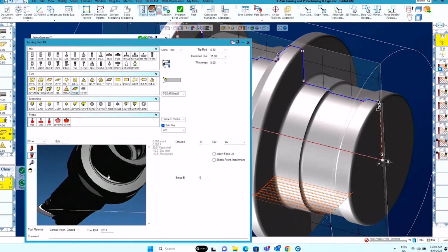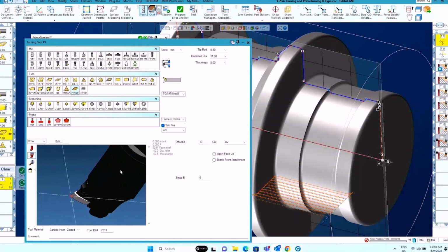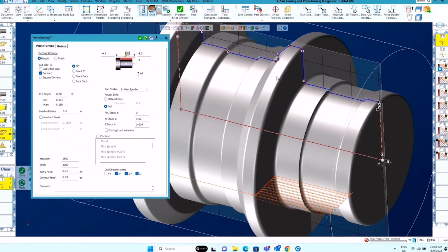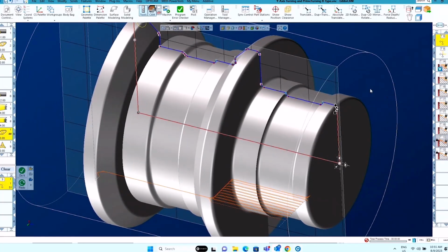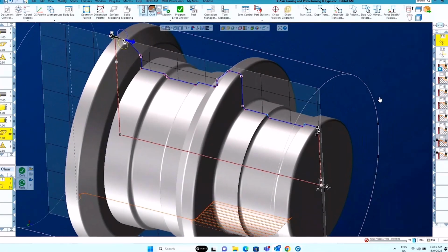It's designed like this, so the system knows automatically that my toolpath has to be created in the y-axis plane and not in the conventional x-axis plane. And this is actually how easy it really is to go from conventional machining within GibbsCAM to y-axis machining in GibbsCAM. Okay, so that was a little bit detailed.